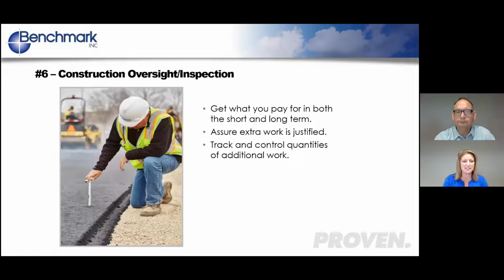So step number 6 is construction oversight and inspection. Having on-site personnel, someone that's managing your project for you, can really assure that you're getting what you pay for, and can be tying that back to the unit price that we talked about, or those quantities of bid in that unit price bid form. So it allows your eyes on the project to also have an understanding of what's going on, to be able to help you justify: is the additional work that's being requested necessary, or are there other options potentially?